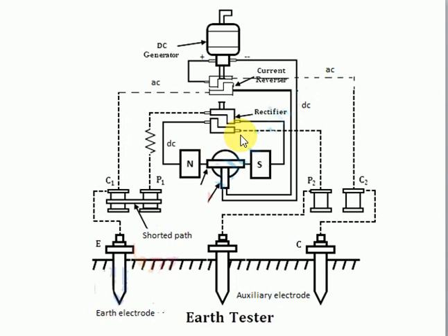So during measurement, I think you have seen the resistance when this point was connected to the earthing point, that time the resistance was very less, which is the desirable one, because the earthing resistance should be less, otherwise fault current will not pass through the ground. And again we have noticed another thing during the experiment. When we place this electrode somewhere at any other place, that point is not connected properly, that's why the resistance was showing more, meaning that point's earthing is not good. So this way we can measure the earthing resistance.